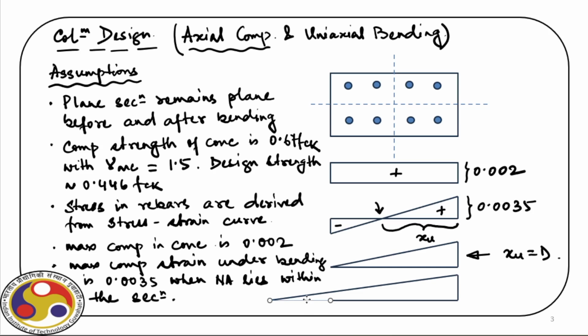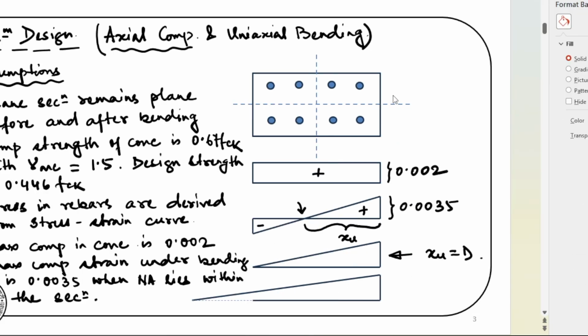and we have to now calculate the stress at this fiber. Okay. Now, if that is the case, then obviously this is no longer 0.0035. So this is 0.0035 minus 0.75 epsilon minimum. This is epsilon minimum.